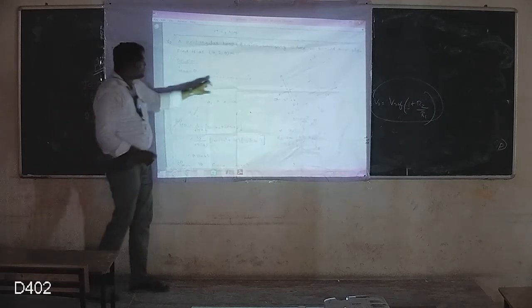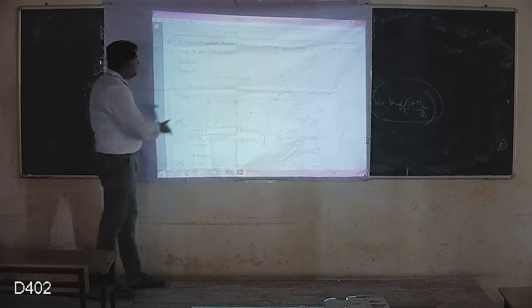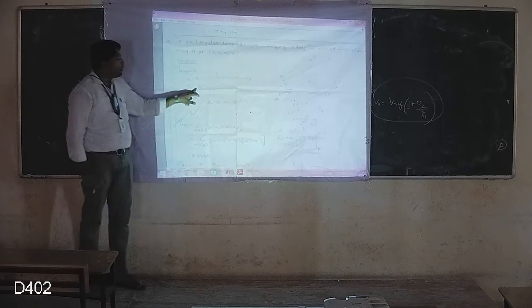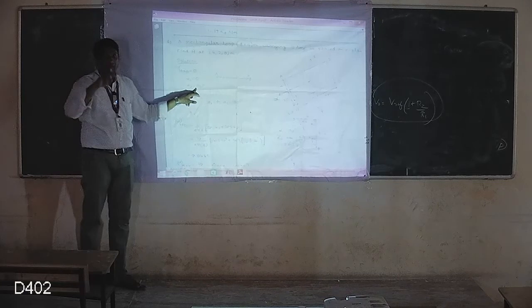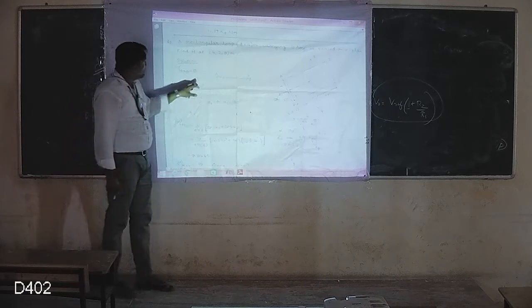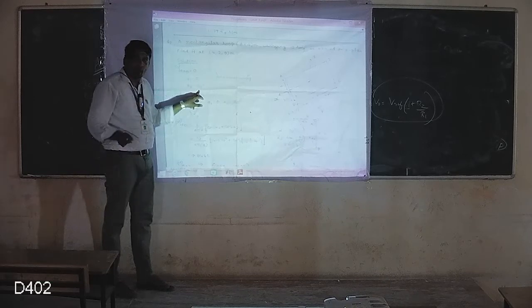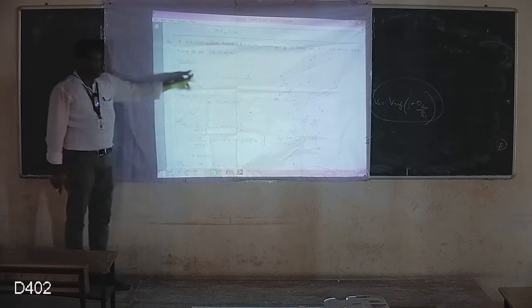So therefore, it is a conductor, and the point is located at the B point, and we can obtain alpha 1 is equal to 0 and alpha 2 is equal to 180 degree. So with the same formula we used in the previous case, I divided by 4 pi r, cos alpha 1 plus cos alpha 2. Cos 0 becomes 1, cos 180 becomes minus 1, 1 plus minus 1 becomes 0, and yes, the complete solution is equal to 0.